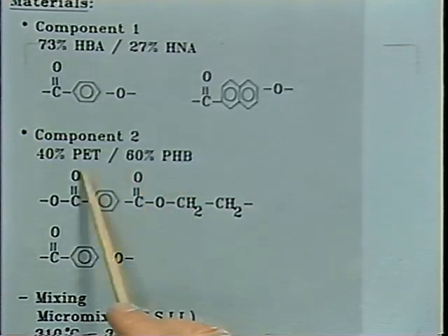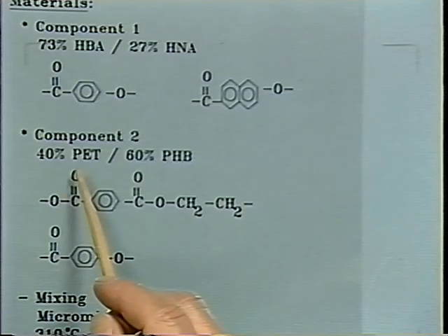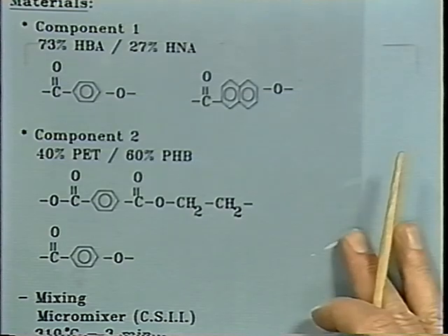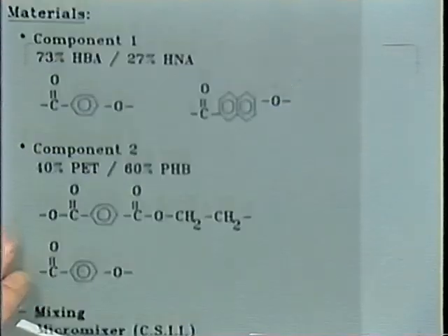It actually is a two-phase material. The mesogen and the PET phase separate in that system. The PET forms an isotropic region and the PHB a nematic region in that system. It has been mixed before performing the rheology. If there's transesterification, then certainly those molecules would be cut and recombined, and we will see a mixture of the properties in a fairly short time.